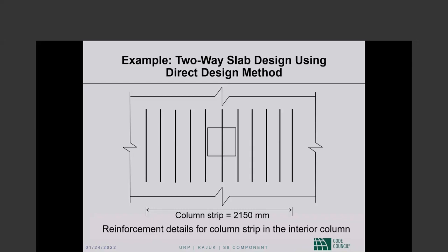Now this column strip moment is a percentage of the slab moment, depending upon which slab section. The column strip moment may be 75% of the whole design strip moment.